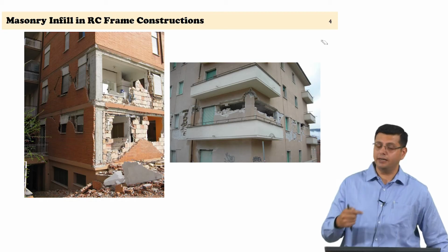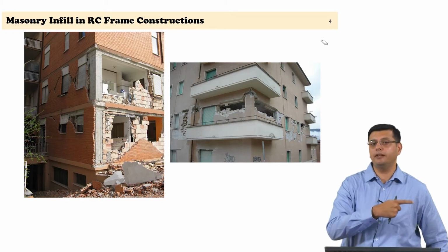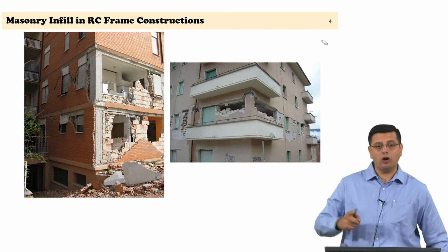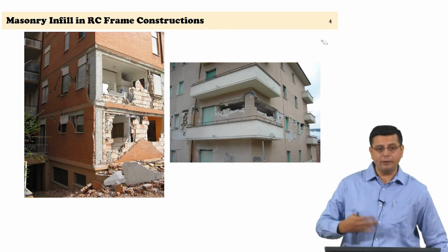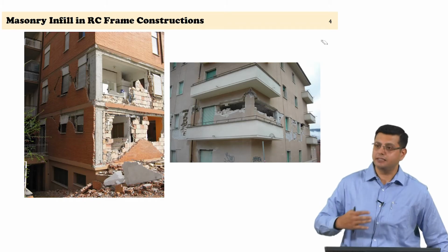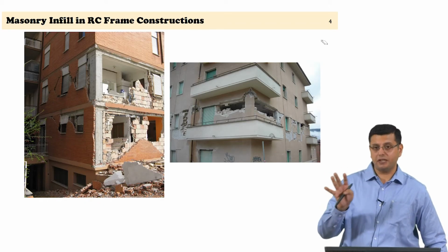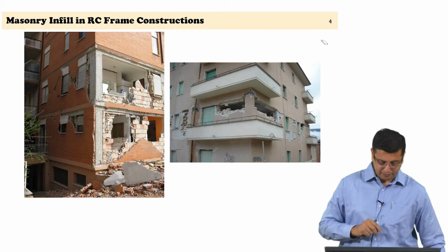So, immediately you would understand that the equivalent strut that can form in a blank panel can be altered with the presence of an opening. However, depending on the geometry of the panel, a partial strut can still form given the position and the size of the opening itself.